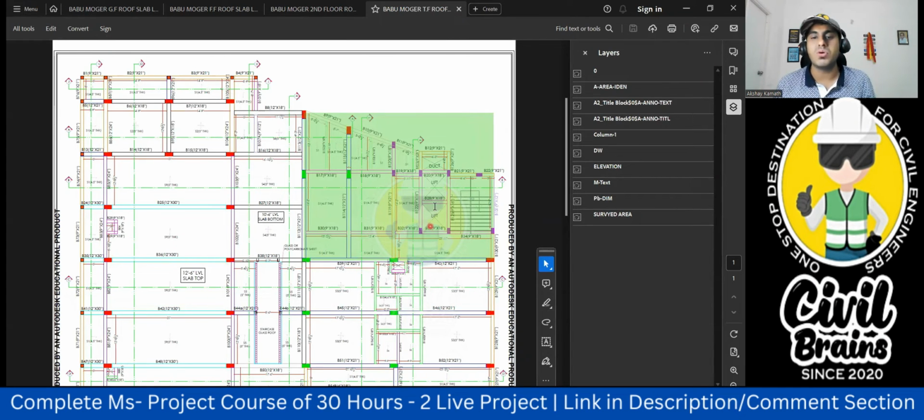That is your MSP level, because so far the lift portion was open, so you need to give a cover, a slab, to the lift. The staircase was also open, so at the top you need to give a slab. That is why that level is called the MSP level. Usually if it is a high-rise building, in the last floor we keep another two or three rooms extra. One can be used for the lift machine room, others for a store room, or a watchman room. But we are not going to use the entire layout.